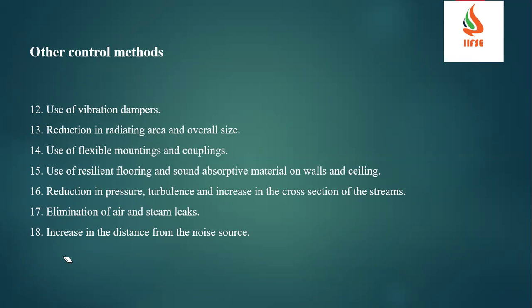Then reducing pressure, turbulence, and also increase of cross section of these steams. Then elimination of air and also steam leaks, and increase in the distance from the noise sources. So these are the various ways we can reduce the exposure.